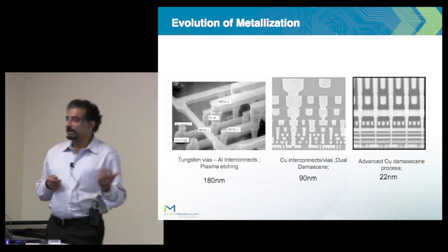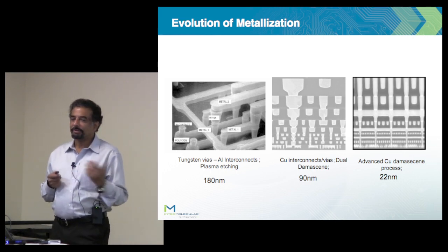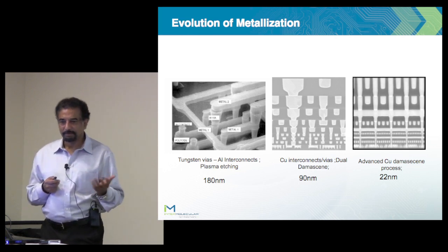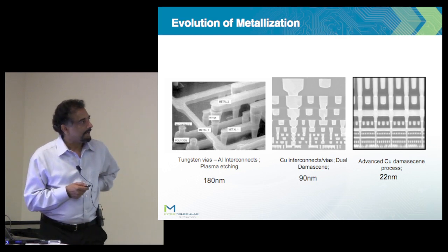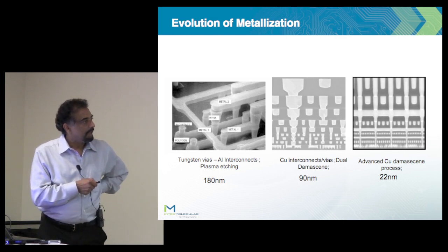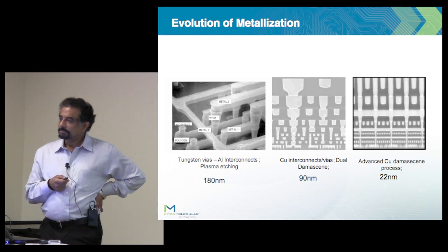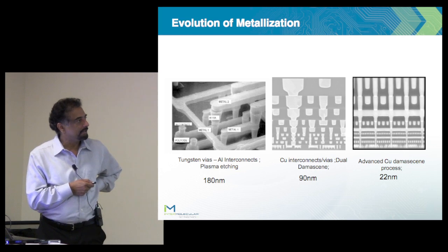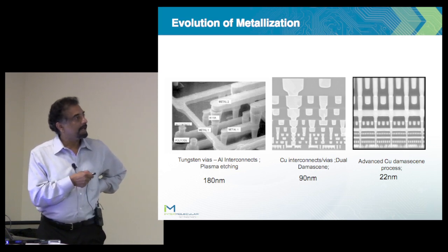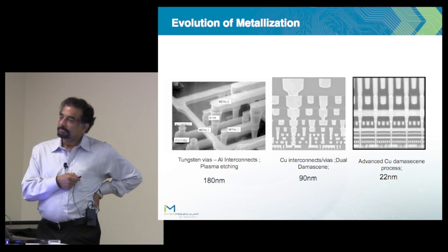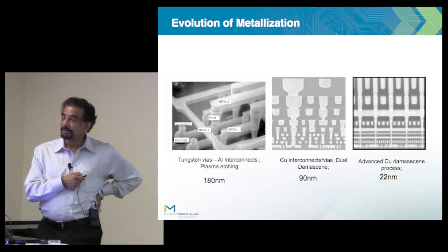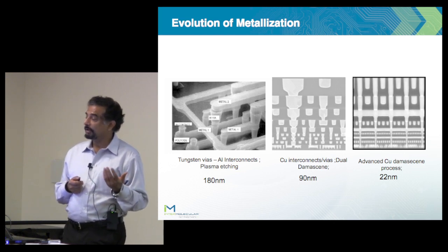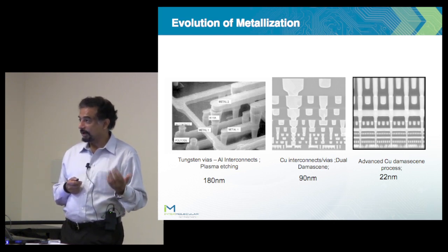In the metallization side, usually most of the materials work, and so I got a big start also by developing quite a few generations of back-end metallization. We started with aluminum and silicon dioxide, but we went through several generations where we introduced alloys and barrier metals. For example, at the 180 nanometer, you had the aluminum and clad aluminum and tungsten vias, and there was a lot of challenges associated with the materials, both the metals and the oxide.